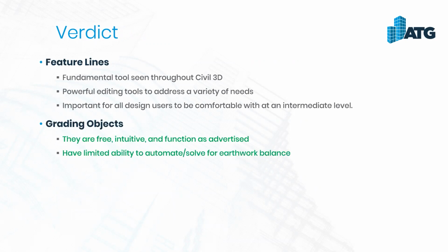You also have a limited ability to solve for your earthwork balance, and that's part of why we're here today. I should not have buried this lead quite so far, but the really cool and interesting thing about our Civil 3D grading optimization tools is that we're now allowed to use our earthwork balance as inputs for our workflow. So we get to say, yeah, I'd really like to have 20% cut or 30% fill. We don't have to use that as an input, but that's part of the attractiveness of using this tool. And our grading objects have a limited ability to include that.